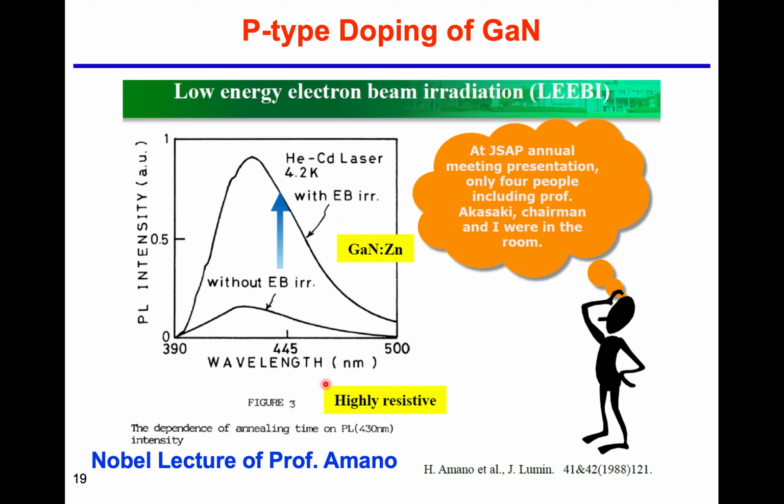And the other thing, there are many interesting characteristics in gallium nitride. The other thing is the p-type doping. Okay, so in chapter 3 we said we can incorporate some group 2 material atoms into the 3-5 compounds, and they can achieve the p-type doping. However, when we put for example magnesium into the gallium nitride, we found there's no p-type doping.